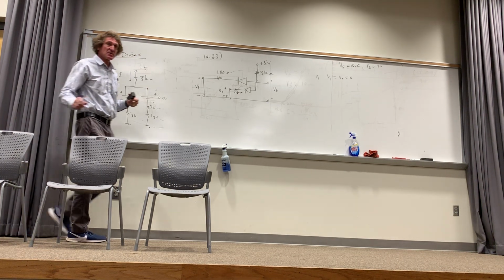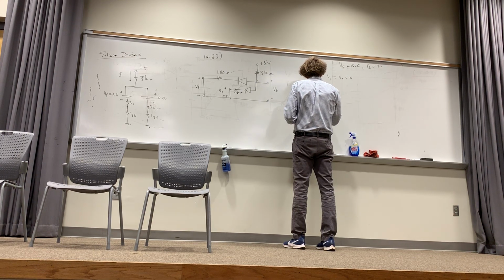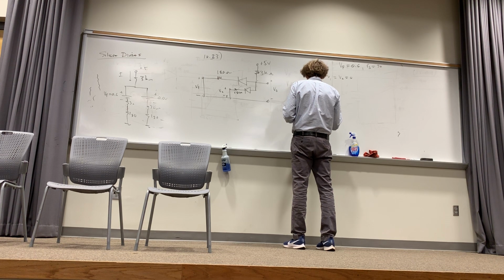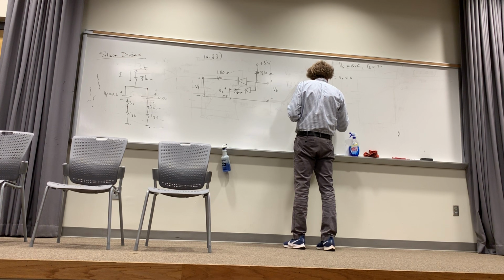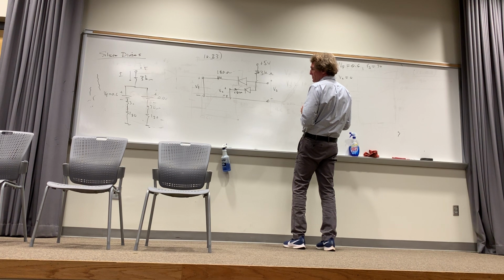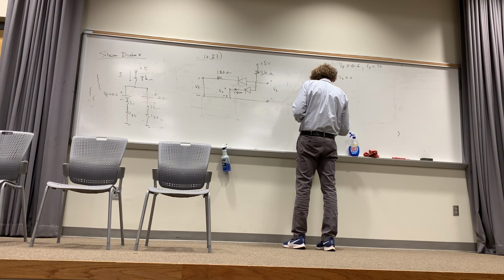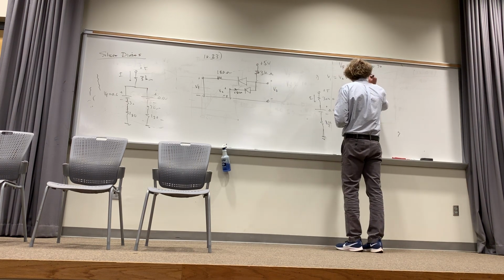So the equivalent of that circuit is this circuit. You can take the 5 volts, put in the 3K up here. You don't have to do it this way, but it's easier. Then I go ahead and say that now I'm going to have that same voltage on both of them, which is 0.6 volts. And because these two are in parallel, now I take 30 plus 180 is 210 divided by 2. So now I take my resistance as 210 divided by 2, and I get the current there. That means the current here would be what?